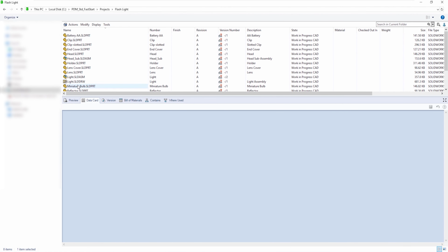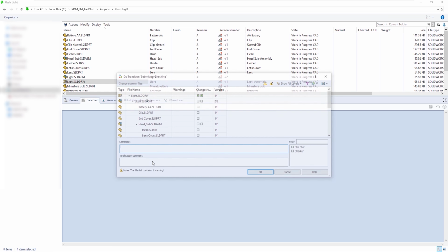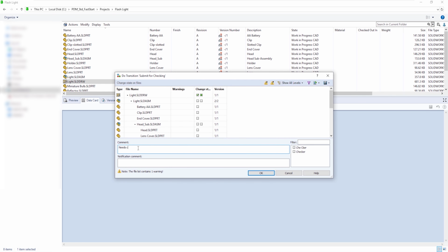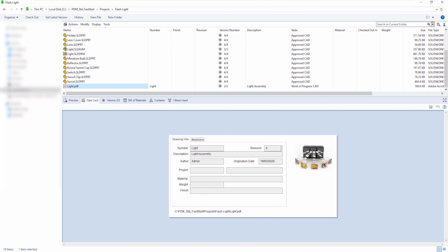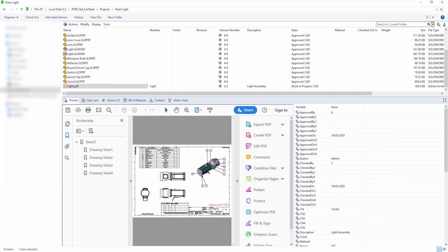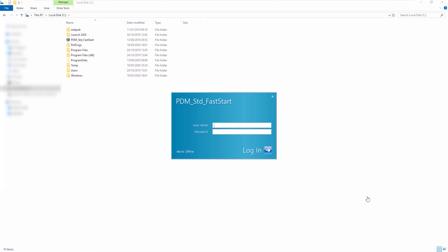We're going to look at the workflow approval process in SOLIDWORKS PDM Standard. We'll see how PDM enables us to control access to documents based on an electronic workflow. This enables us to streamline company procedures and processes, gives access to the data when it's needed, and enables approval control. It gives us the ability to automatically capture key approval information to write to the drawing border and automatically generate PDFs. We can use the electronic workflow to limit or grant access to files based on the electronic state that the file is in.